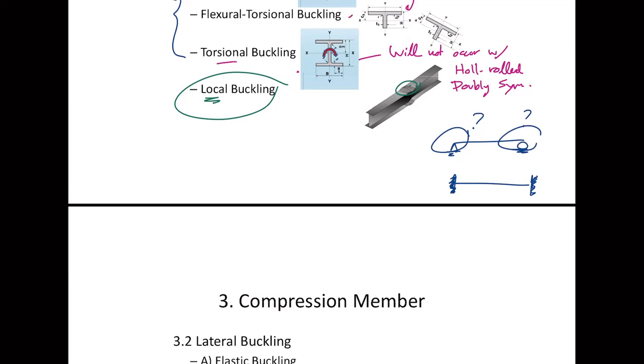So perhaps not. I think this is a very good question, so let me try to explain it right away this time. First, for steel structure, I don't know much about concrete, but for steel structure, when you want to build a simple beam like this, the way you give details must ensure that a large enough rotation can occur. They used to give the number in the specification, say 0.3 radian.